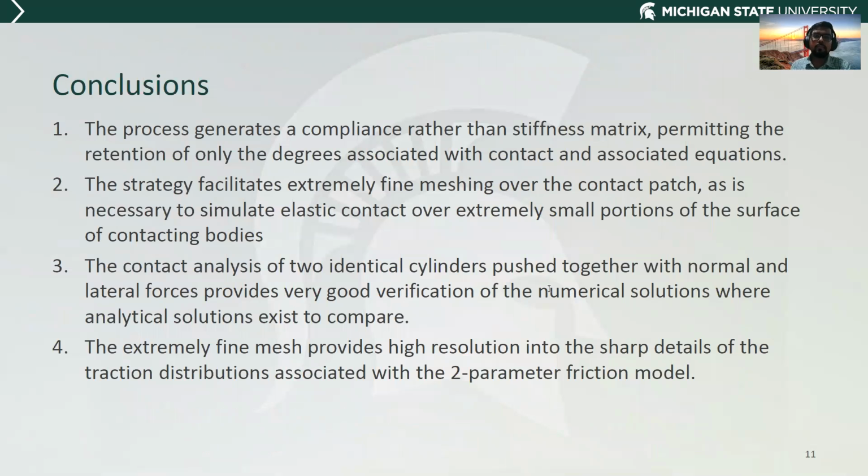So in conclusion, the process generates a compliance rather than a stiffness matrix, permitting the retention of only the degrees of freedom associated with the contact and an associated equation. And we can drop all the equations where the nodes are not in contact. The second thing is the strategy facilitates extremely fine meshing over the contact patch, as it is necessary to simulate elastic contact over the extremely small portion of the surface for the contacting bodies.